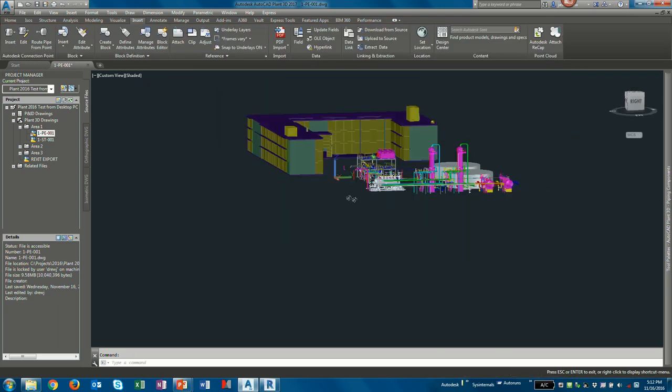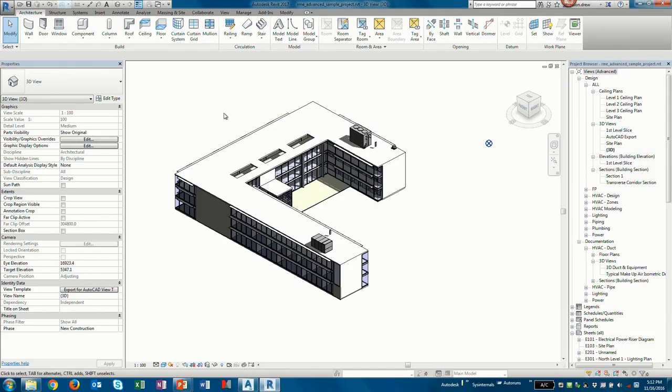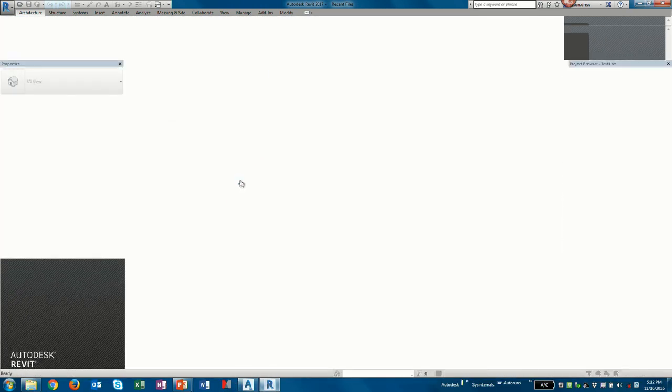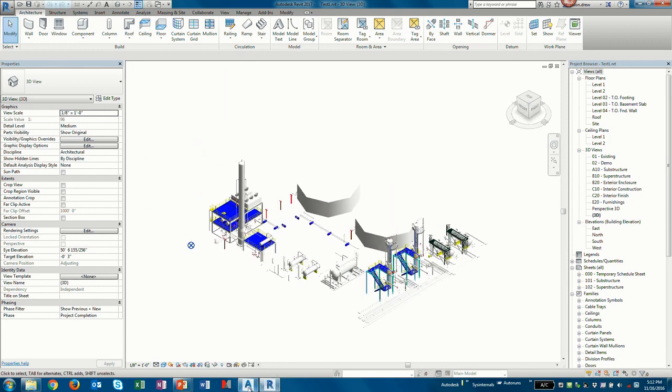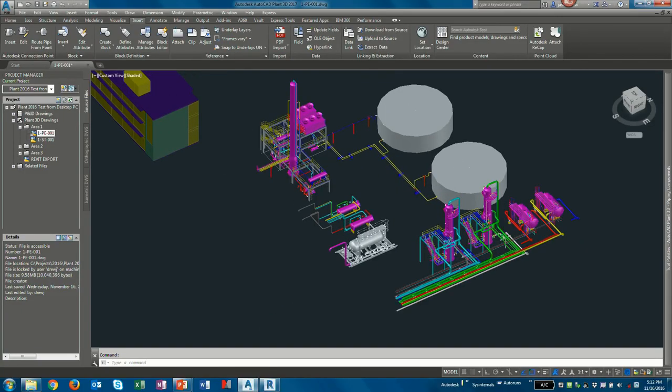Okay, so one thing we'll look at is what happens after I have an update in the drawing file that I've brought over to Revit, back to DWG Sync. Let me go back over here. I already had this one loaded earlier. Let's say somebody makes a change in the drawing, somebody routes some pipe, makes some changes, things like that, and I want to update this. So let me go back into this model. I'll just make one change, like draw a line in here.